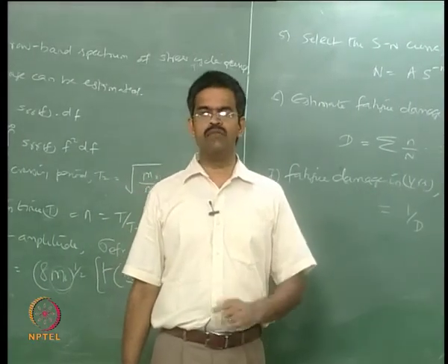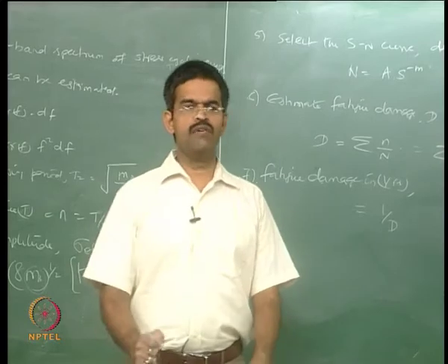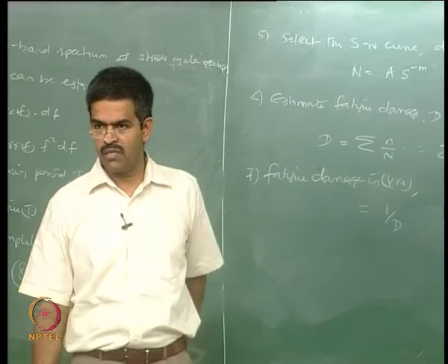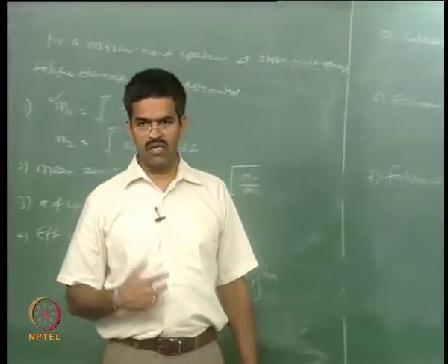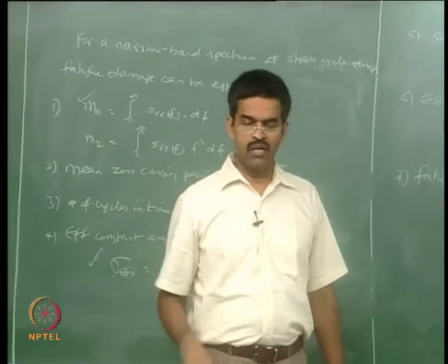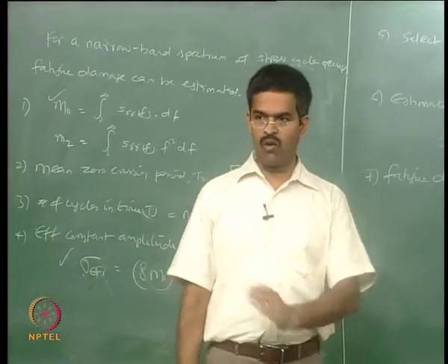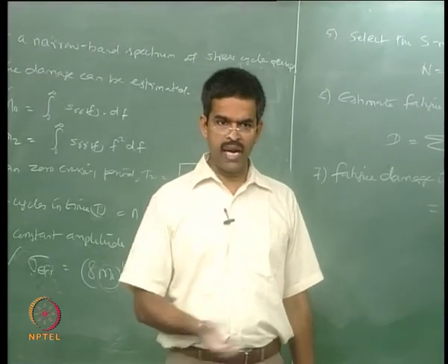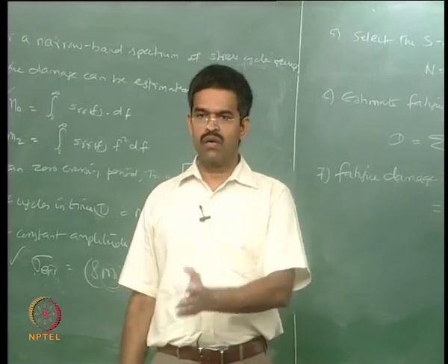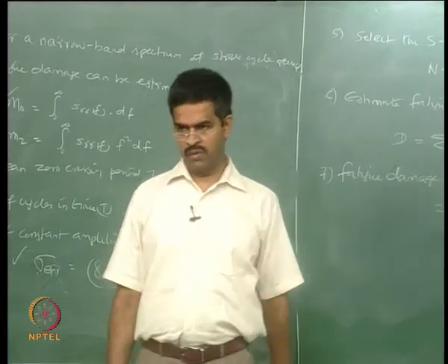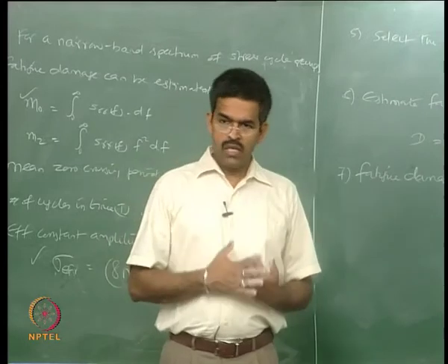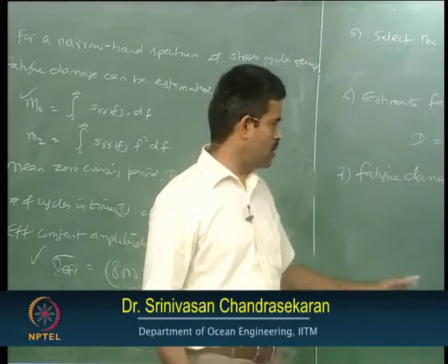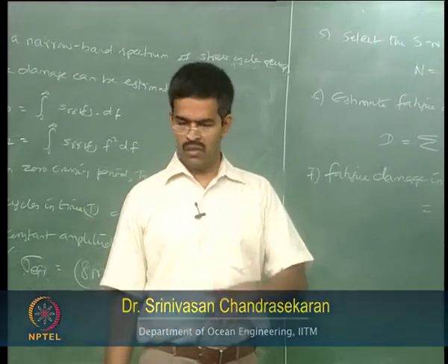Now in this lecture we understood why at all we go for a spectral fatigue damage, why not a time series. In the last lecture we discussed the time series estimates of fatigue damage simply by the rainflow counting technique, where we understand only the peaks and valleys. In this case I cannot handle it, because if it is a dynamic loading as in the case of wave or wind, the response of the structure excited under this band of near resonance frequency will not clearly give you a correct picture of the damage. So I must look for a stress cycle spectrum. It can be narrow, it can be broad. If it is narrow, I know how to handle it. If it is broad, how to handle it, next lecture we will discuss this.